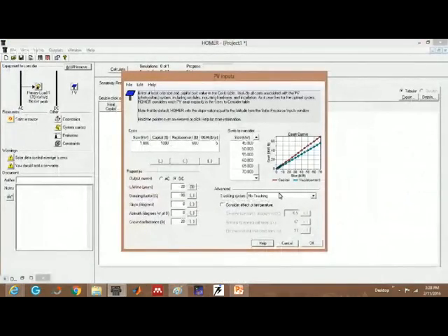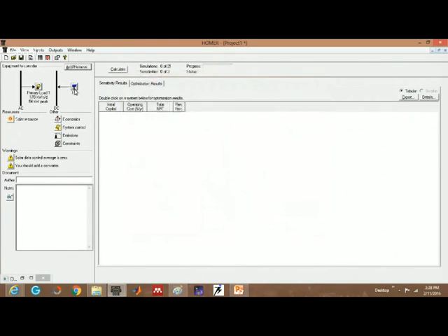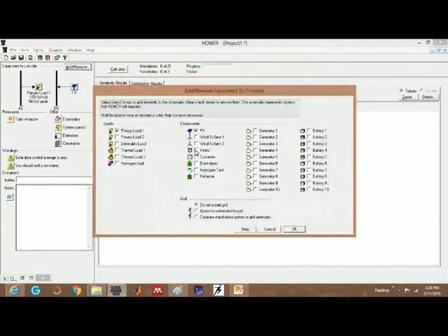So now, so far what we did is we have put, let's say, up to 70 kilowatt panel maximum. This is the maximum value of solar photovoltaic panel I am providing to Homer. Let's say the system is not feasible, so it will give me some warning that this is not a feasible solution. Please add some more photovoltaic or some battery, something like that, right? So once you have decided the solar photovoltaic, now you can add, let's say you want to add some battery.